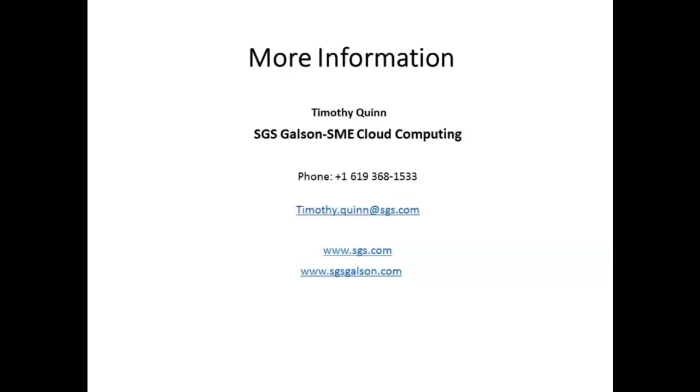Okay, great. Our next question is, can you apply your IoT systems in potentially explosive atmospheres, and are they intrinsically safe? The answer right now is no, but it will happen. Intrinsically safe devices are very expensive to build, design, and certify, more importantly. The market is not that big. It is in the oil and gas industry, and they usually trail behind consumer, corporate, industrial grade devices. So the answer is not at this point. I don't know any cloud-based devices that are intrinsically safe at this point, especially for confined space.